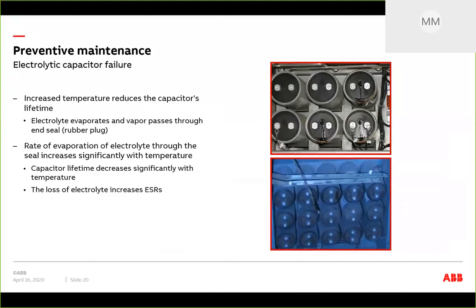It's just aging, so that can lead to a very serious problem, or it usually starts with an intermittent problem where they're getting a DC undervoltage, or if it's shorting, a DC overvoltage. See, that's what we're saying: we can measure those variables, and this is where the machine learning kind of stuff comes in. We know these are bad, then we go look at the data and say, hey, this is flaking out, let's look at these.